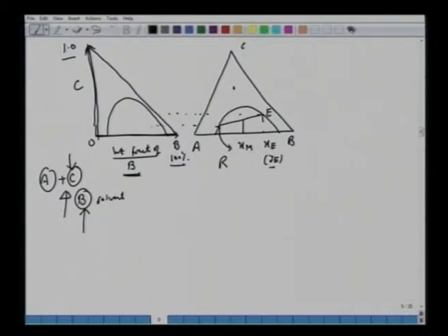Still you have the phase diagram, you have a tie line, so you have extended this here as extract. You take this raffinate all the way till here, you have the tie line on this. You have this M as this. So this will also work as a representation of this extraction system with this as raffinate phase here. Here you will have extract phase, you will have XR, you have XC, except now the amount of A we have to calculate from 1 minus whatever B you have, whatever C you have here.